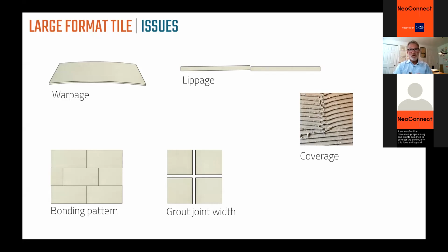The larger tiles need to have full adhesion and full support. In other words, full coverage of thin set mortar. And we'll talk about what full coverage means. It could mean 80%, it could mean 95%, depending on if it's a dry area, an interior non-wet area, or a shower, or an exterior, it would require 95%. But it's very important that large format tiles be supported and adhered with enough thin set.